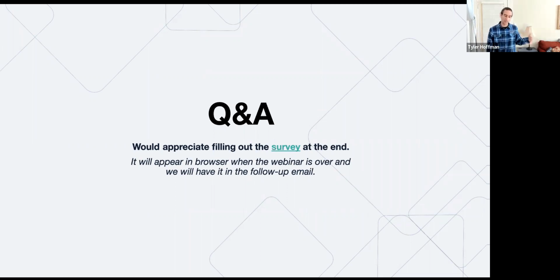And then just extrapolate with math. Yes, I will say, and hammer it home, at Fitbit, the way to validate battery life was to wait the full 7 days. If our battery was supposed to last 7 days, we didn't ship a firmware until all the devices running that firmware lasted 7 days. We'd tell all the firmware people and a bunch of test people, charge the device, here's a new firmware, and then report when your device drains completely, or we'd have that in metrics actually.